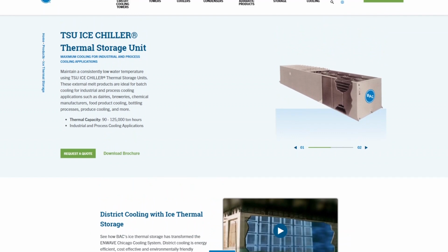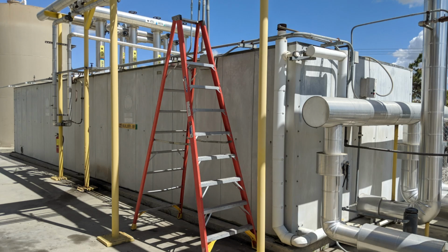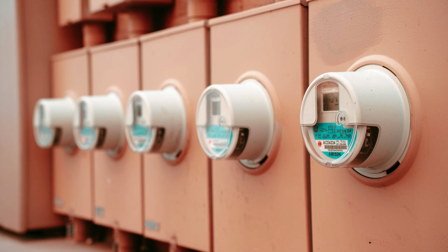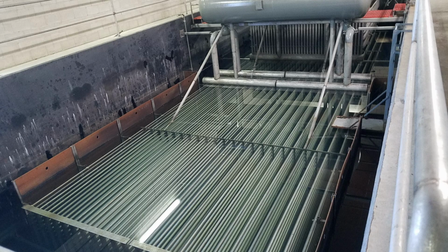Water surrounds the pipe coils within the tank. During the ice formation phase, cold liquid refrigerant circulates through the pipe coils, absorbing heat from the water and causing it to change state into ice. The ice formation phase is typically performed at night when electricity is least expensive. Then during the day, when electricity is most expensive, the refrigeration to the ice builder will be shut off and the ice is allowed to melt as water is pumped through the tank and out to the plant to provide chilled water where needed. Ice builders are only attractive in situations where energy costs vary throughout the day.